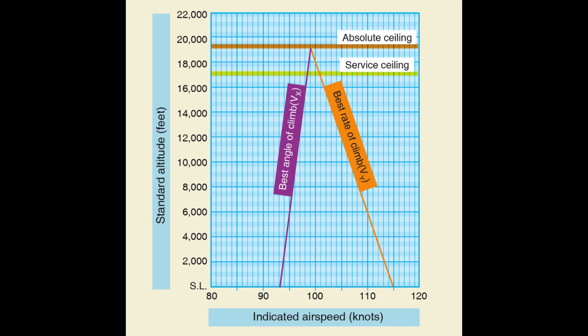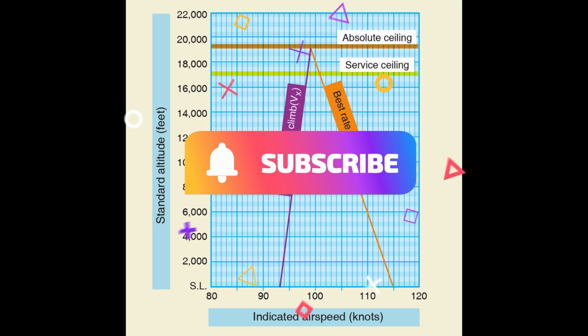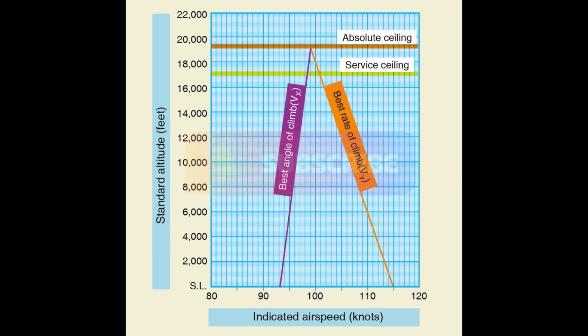Engines that are normally aspirated experience a reduction of power as altitude is gained. As altitude increases, air density decreases, which results in a reduction of power. The indications show a reduction in revolutions per minute (RPM) for airplanes with fixed pitch propellers. Airplanes that are equipped with controllable propellers show a decrease in manifold pressure. The pilot should reference the engine instruments to ensure that climb power is being maintained and that pressures and temperatures are within the manufacturer's limits. As power decreases in the climb, the pilot continually advances the throttle or power lever to maintain specified climb settings.